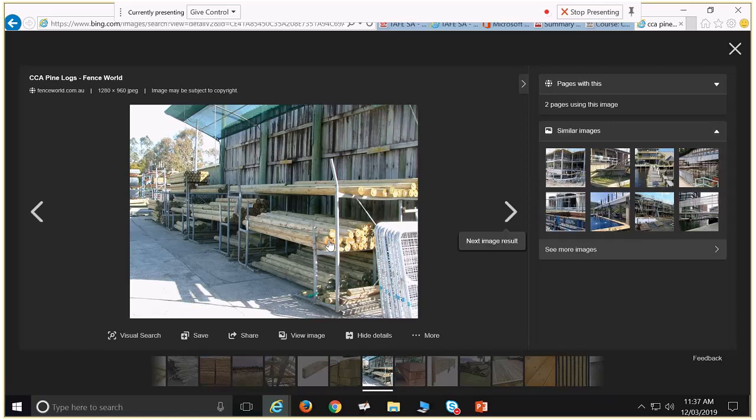Stuff like that is used a lot. If you've ever been through a vineyard, you'll see lots of it. It's treated with copper, chrome, arsenic, all of which are probably not particularly healthy, the latter the worst. But, of course, termites don't want to eat it. You put that in the soil, it's going to stay fairly well. So that's one approach. You can dig holes and ram posts in there to bypass some of your active soil, and pick your house up. That's one way of doing stumps.